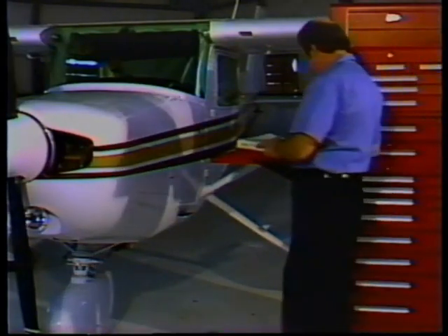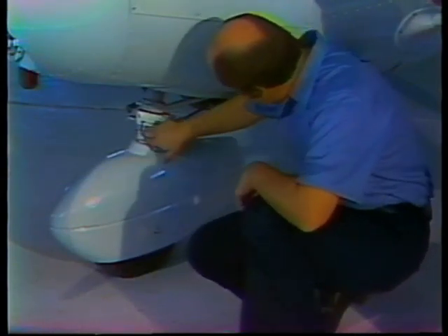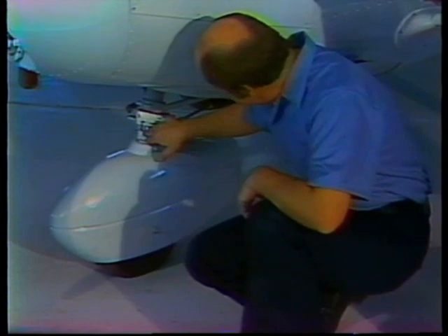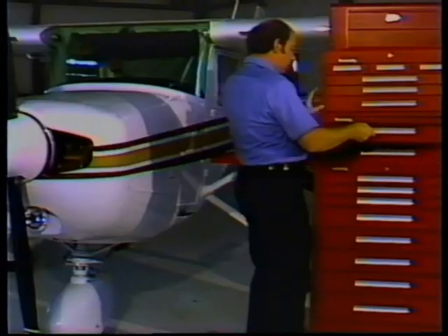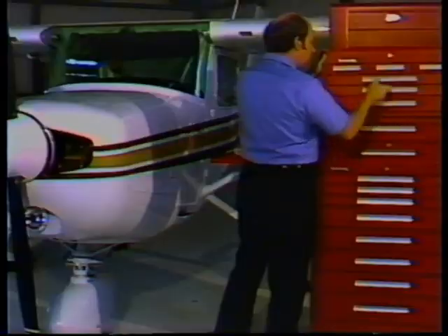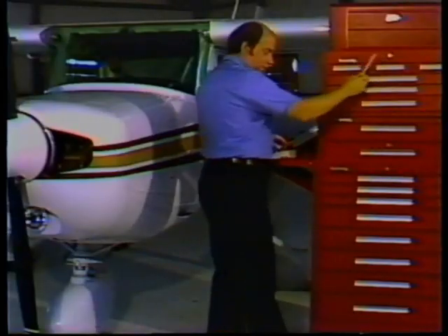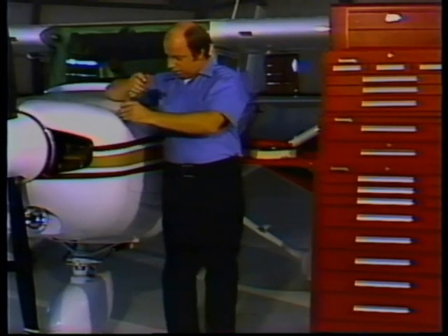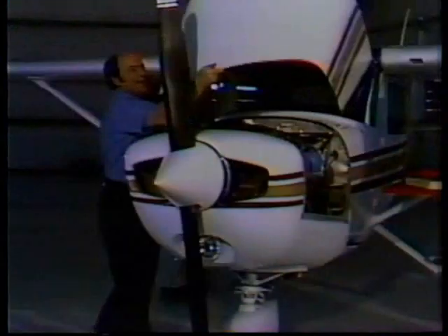Shock strut servicing is one of many simple operations performed by aircraft maintenance technicians many times during their careers. As with any job, the first task is to select the proper tools and service information. Servicing should be accomplished on level ground, ideally in the hangar. Open the necessary inspection plates or remove the cowling as required to gain access to the air valve located on the top of the strut.